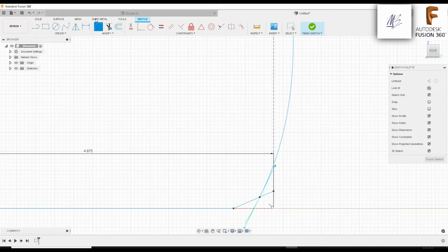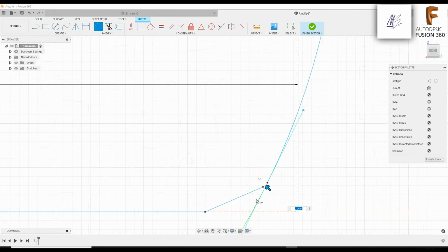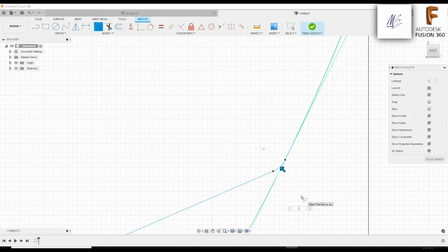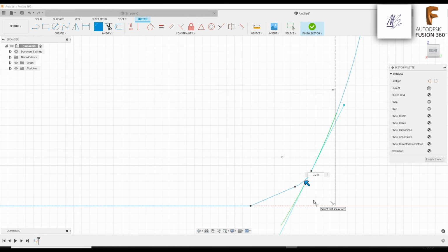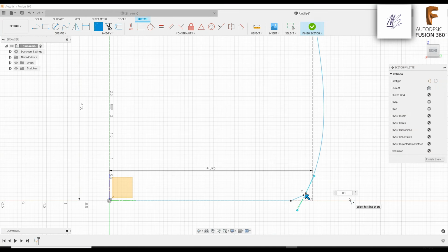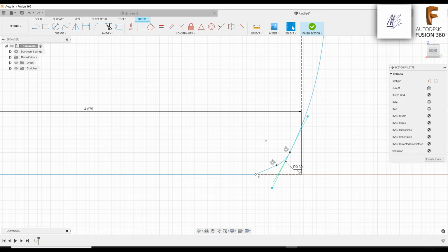So if you left click on fillet up here, you get the option to create a fillet. All right, it's another constraint, and then you kind of choose your radius. Okay, so nice. That's decent. You don't have to be anything extreme. That fillet is like 0.2. Let's do, what's 0.1? What does 0.1 look like? 0.1 is decent, but let's see what 0.3 looks like. It's not bad.